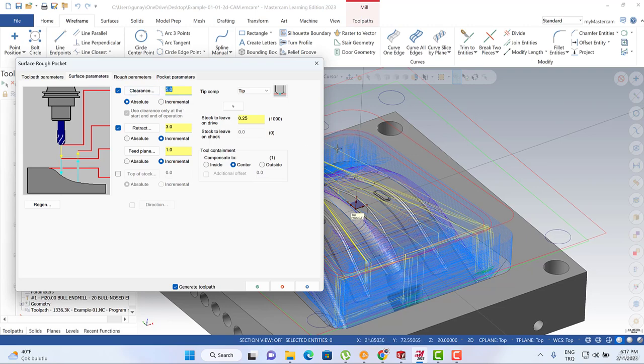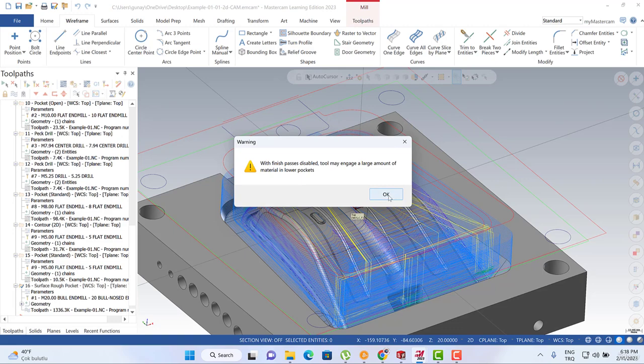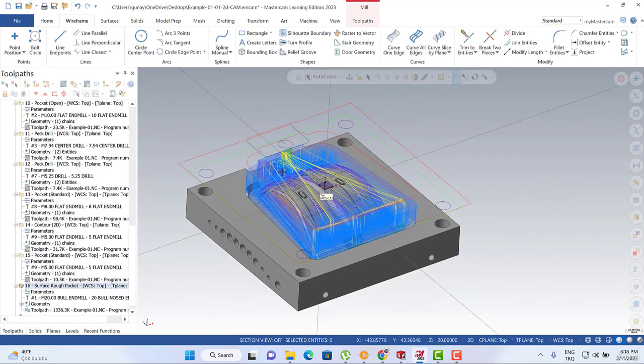You can also see it here, and then after that we just need to focus on the feed position by using the retract position. So G0 is going to be used here. After that we just need to move with G1 linear interpolation only 1 mm, and then we can keep going to cut our surface. Okay, that's it, and this is for the roughing process.